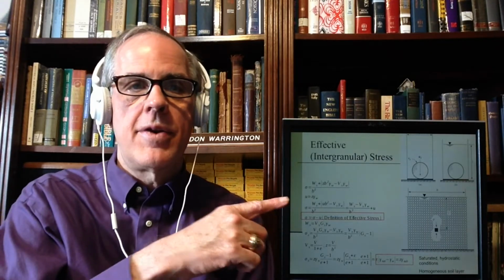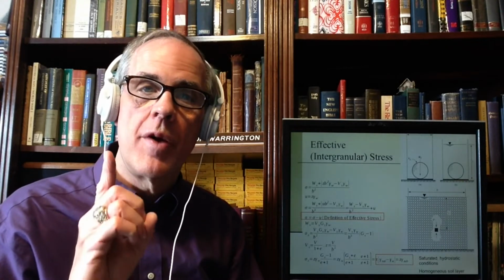I do go through a lot of math, and I show the math here, and if you're interested in it, you can look at it. But basically, what I can show is that in the end, we're going to define the effective or intergranular stress of the particles as equal to the total stress, which we defined just before, minus whatever pore water pressure is between the particles. Now, pore water pressure, we're going to start with hydrostatic. It doesn't have to be hydrostatic, but for our purposes right now, and for most geotech purposes, it is.